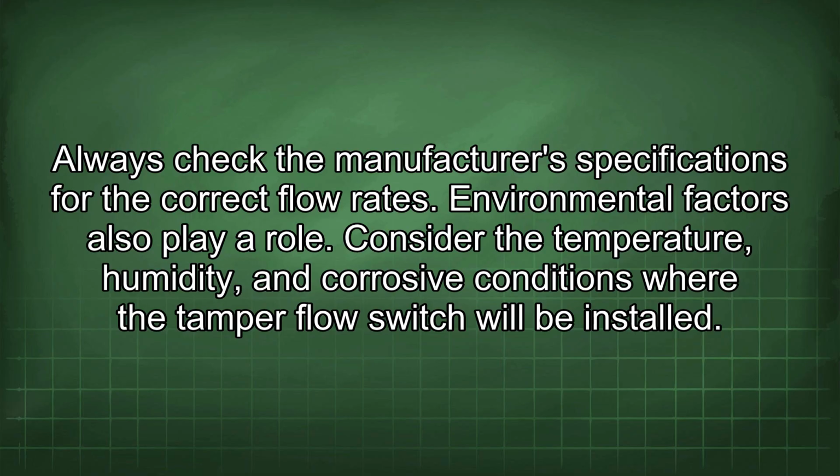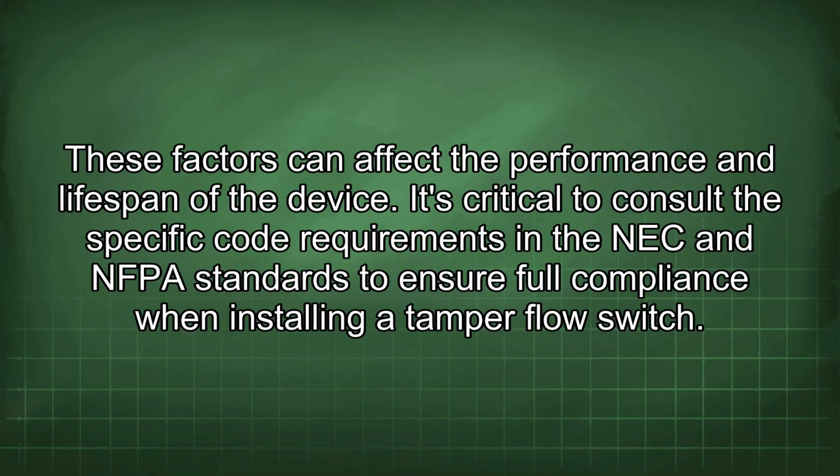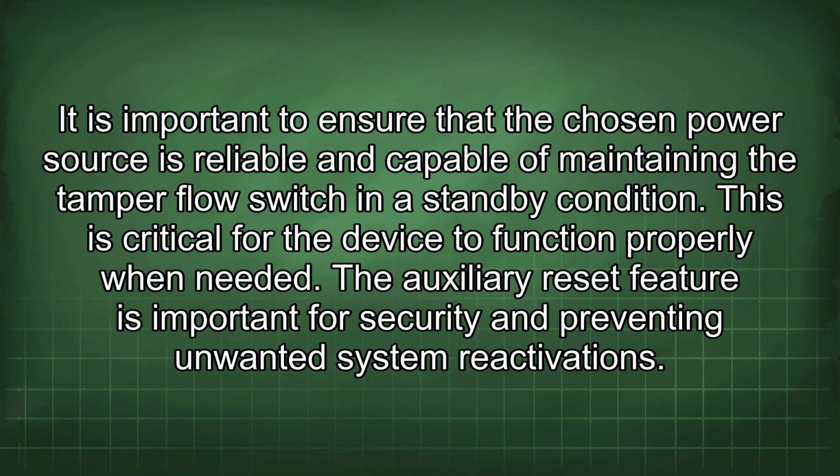Environmental factors also play a role. Consider the temperature, humidity, and corrosive conditions where the Tamper flow switch will be installed. These factors can affect the performance and lifespan of the device. It's critical to consult the specific code requirements and the NEC and NFPA standards to ensure full compliance when installing a Tamper flow switch. It is important to ensure that the chosen power source is reliable and capable of maintaining the Tamper flow switch in a standby condition. This is critical for the device to function properly when needed.